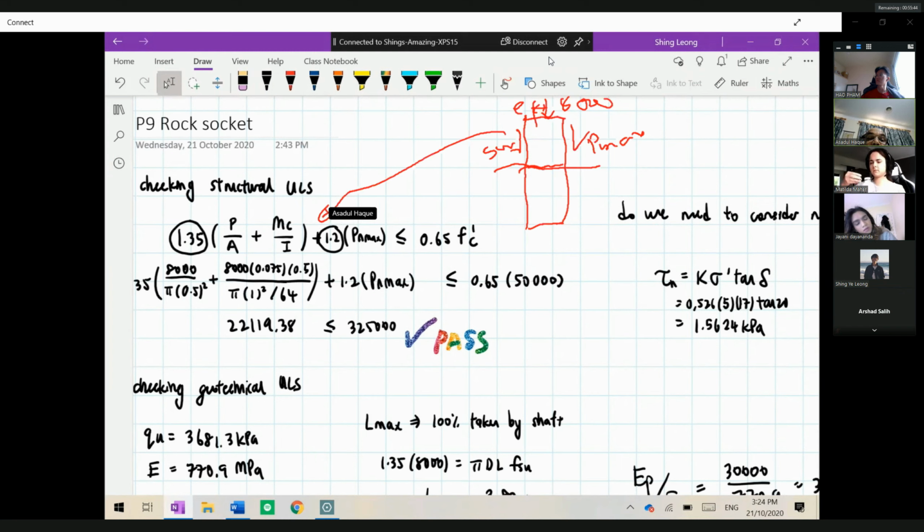So this part is the compression on the top and the positional tolerance due to the bending. So that is the bending stress, and that is the compressive stress that is developing. You have got a multiplier of 1.35 because that is the combined load factor. Then we know that for negative drag down, we have a load factor of 1.2, almost identical. Remember, that is close to your dead load.